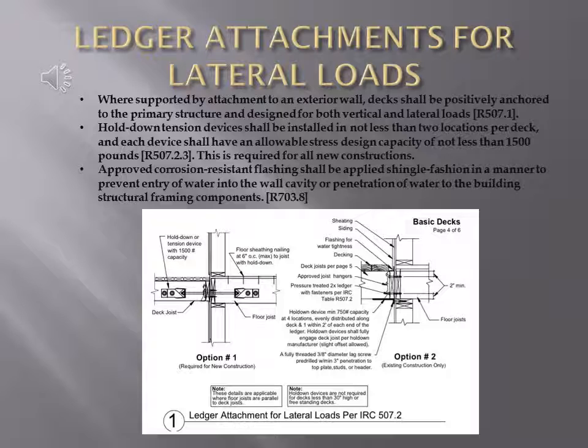Ledger attachments for lateral loads. This is the most critical part of the deck project. Not only does the ledger board hold up the vertical weight of the deck and all the people on it, but it also prevents the deck from detaching from the home and falling into the backyard. The deck is supported by attachment to an exterior wall.